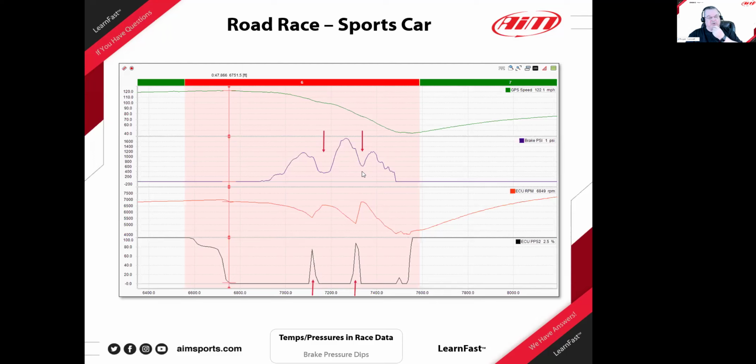under the braking. So I just wanted to make sure that you're not just looking at a maximum braking pressure, a pretty good number here in this case, 1800 psi, but how it is developing throughout the range of the brake. So everybody keep looking into it, maybe study this a little bit, and look at your areas where you're braking and downshifting at the same time, so that you don't have this little problem here.